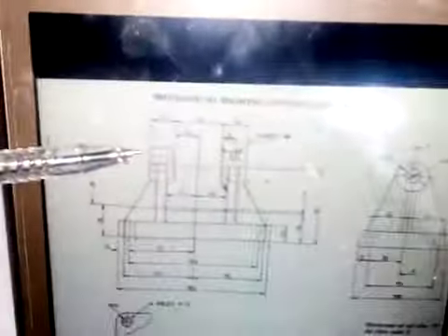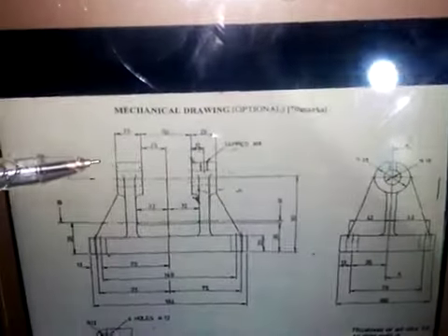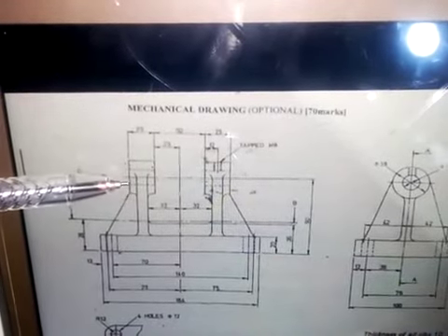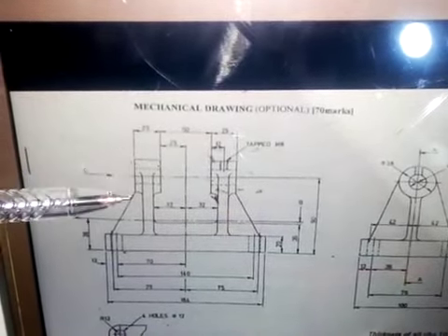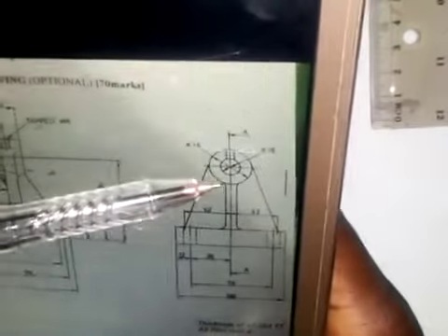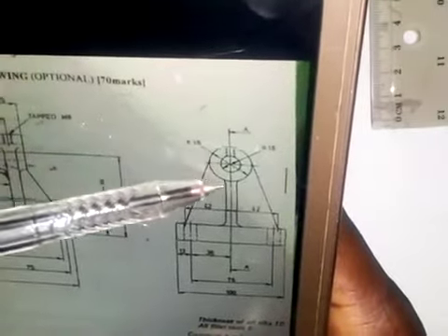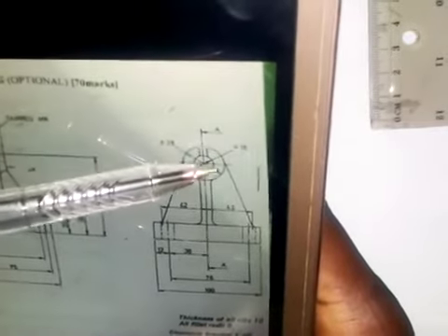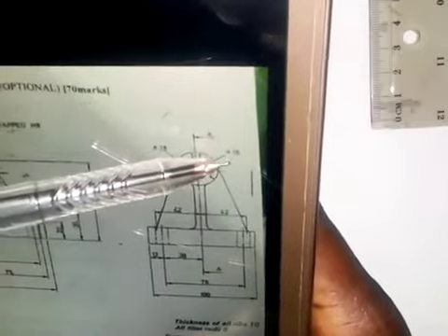All right, so then the height from here to here. So from here to here, we have gotten the center. The height from here to here is given in the end elevation. Here we have that for this outer circle, the diameter is 38. For the inner circle, the diameter is 18 millimeters.